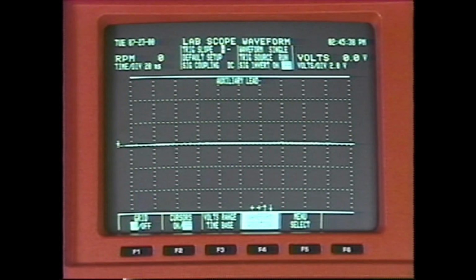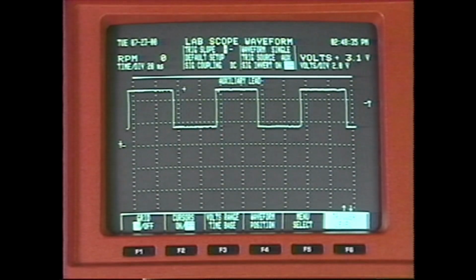A straight line at 0 voltage indicates an open circuit or problems with the power supply, perhaps caused by corrosion. Monitor voltage at different test points in the circuit to determine the voltage drop. If the whole waveform is floating above or has settled below the 0 volts baseline, look for a poor external ground. Be sure to check the ground path between the actuator or sensors and the controller.